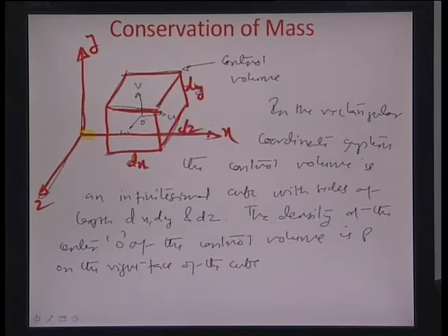Okay. We further assume this point O around which this control volume is symmetrically spaced, and we have 3 components of velocity u, v and w. It is a 3-dimensional flow. This is the origin 0 0 0, and we are trying to investigate what happens at this point O. So, the very first thing that we would like to investigate is the density. Given we have a density rho here at point O, what would be the density at x plus dx by 2, which is this particular face here.